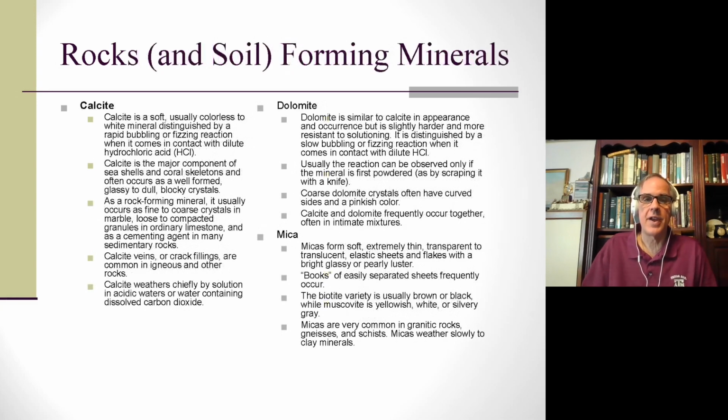And then there's calcite. On the other hand, it's a colorless to white mineral. If it comes into contact with hydrochloric acid, it will generally dissolve in one way or the other. There are two very important types of soils we see calcite in. One of them is calcareous soils, which are seashells, coral skeletons. These are living creatures that have died.